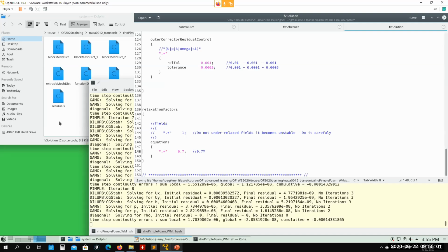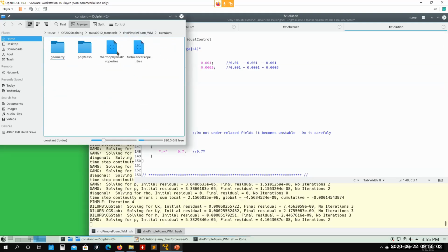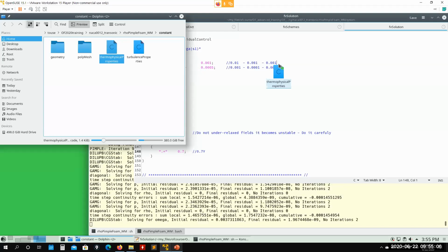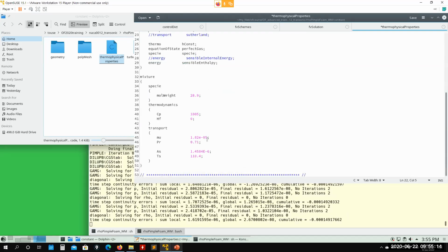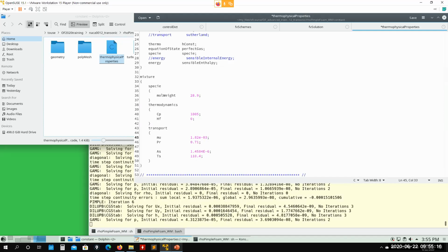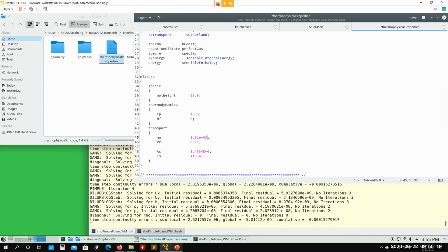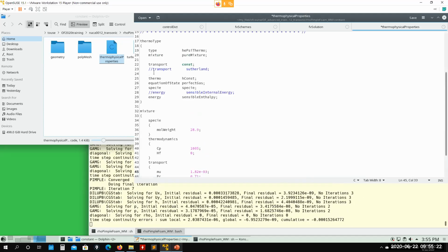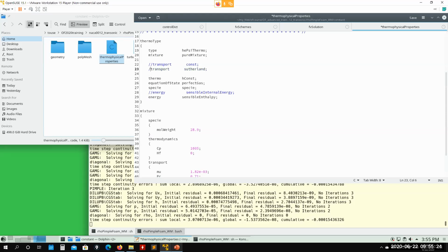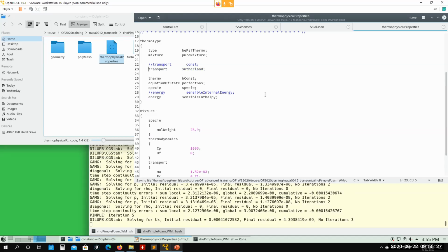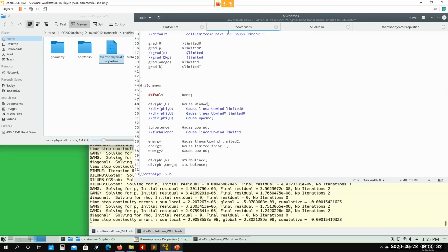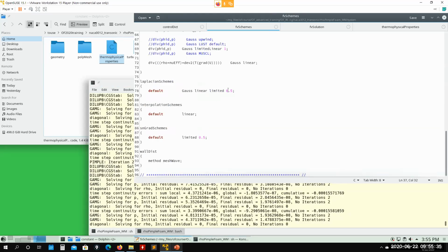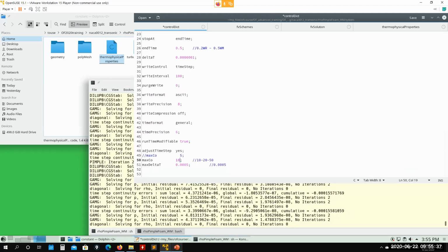By the way, another stabilization technique for compressible cases that I have found is that sometimes you will also need to increase your viscosity. So when you start your simulation, you can use a constant viscosity and put here a large value, 10 to the minus 3. And then, probably after 500 iterations, I slowly reduce it. And then you change to your thermophysical model, the Sutherland model, okay? So that is another way to stabilize. But see that it's running very smoothly. Large time step compressible flow with shock wave. And let me go here now, 18.